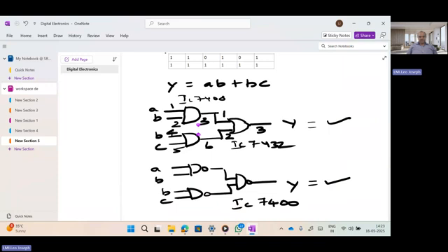So this B and B are common. Even though B and B are common, both have separate inputs. So I have to short this second pin and fourth pin. Instead of giving separate inputs, these two pins are shorted together, right? This is also B, this is also B, a common point. So 2 and 4 are shorted. The fifth pin will be my third input, and this hierarchy we need to connect. I think the connection is now okay. So the third pin I need to connect to the first pin of IC 7432. But before going to this, the second pin and fourth pin should be shorted. That we will see now.